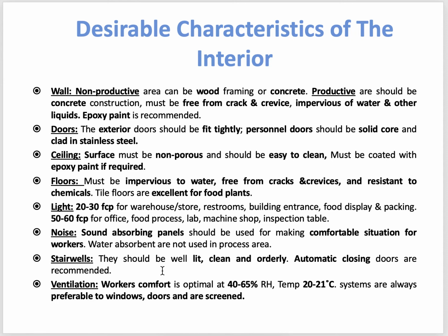Then ventilation. There should be proper ventilation, because if the ventilation is not okay, the environment inside the plant will be really uncomfortable, and it can even become unhygienic. For workers to work comfortably, the optimum RH, relative humidity, should be 40 to 65%.